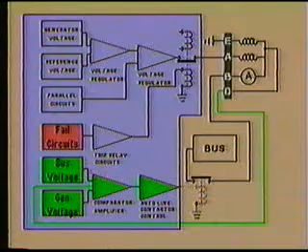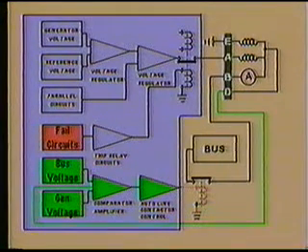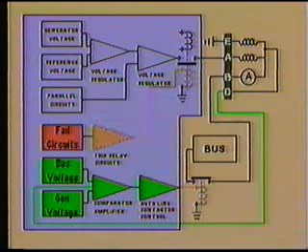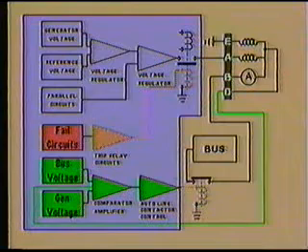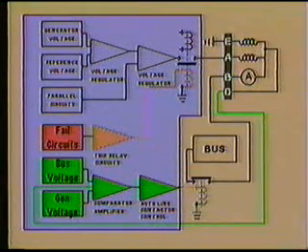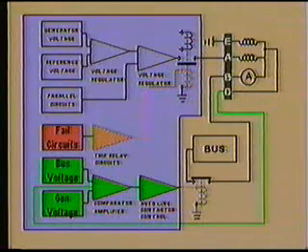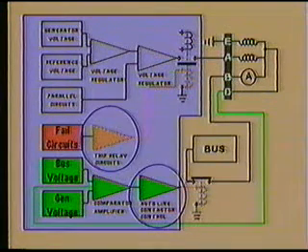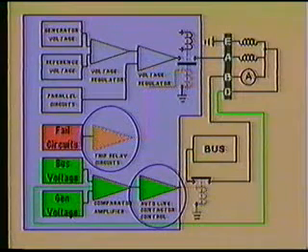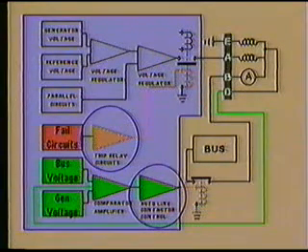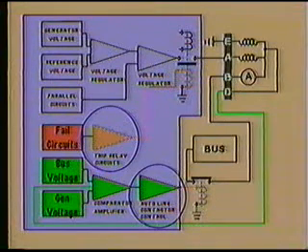Fail circuits are included in the control panel that receive input from several external sensing circuits. If a failure is sensed, the trip relay circuit will become active and disconnect the field of the generator by opening the trip relay, also installed within the control panel. The combined efforts of these two circuits, the auto line contactor control and the trip relay control, prevent the generator from coming online or remaining online if a fault condition occurs.